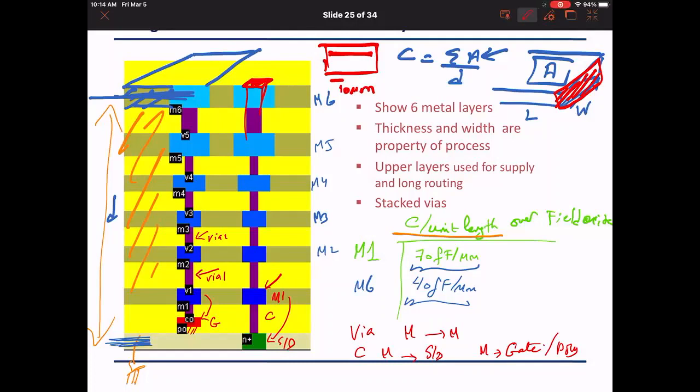Okay, thank you. Anybody has any other question? Professor, at what layer is the heat generation the greatest? At the bottom or at the top? Well, it depends on the chip. Typically in the lower layers, because we have dense metal 1 and wiring, and maybe the VDD network is on metal 2 typically or metal 3.